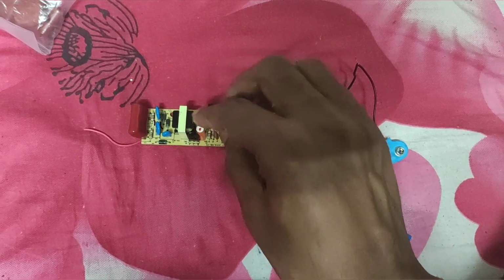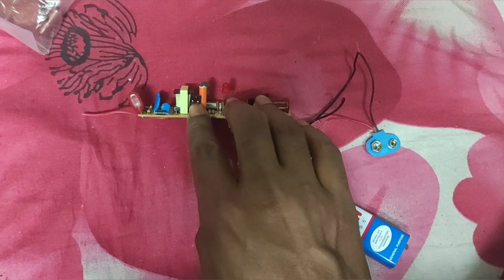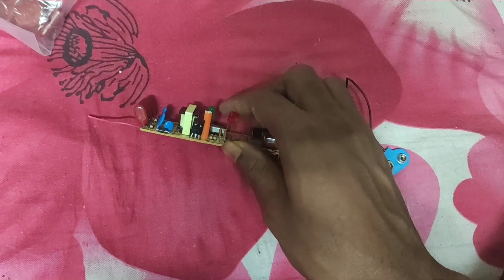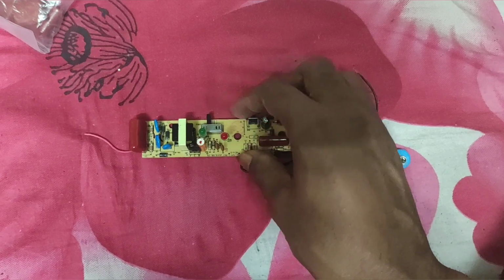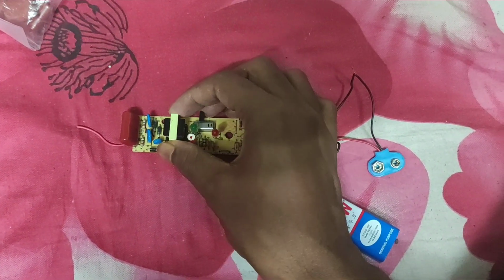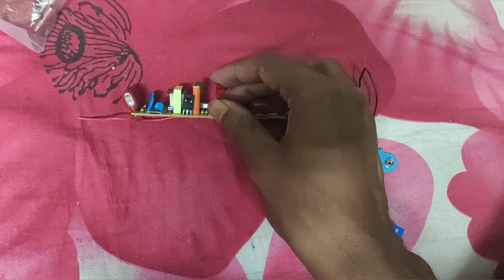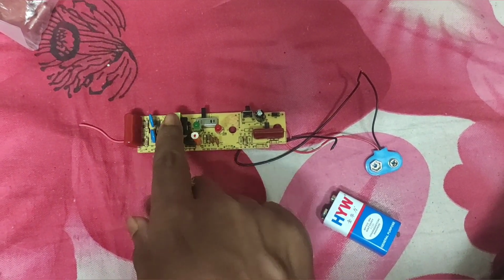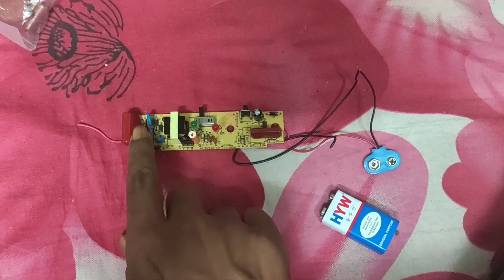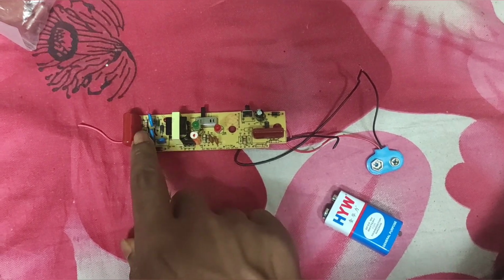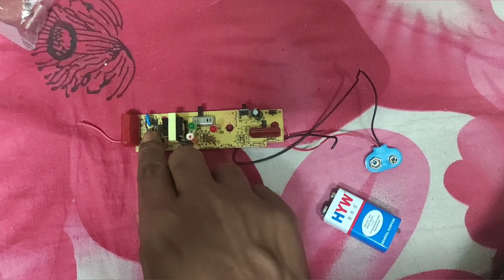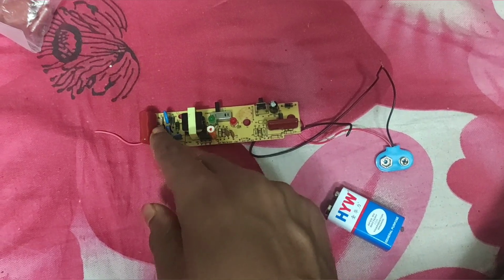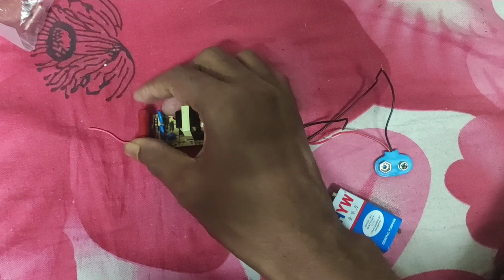The transistor converts this DC signal from the battery to a high frequency AC signal, having a frequency of near about 4.2 kilohertz. So it has a very high frequency, and this iron core transformer converts the low voltage to high voltage and low current. Then it moves from this transformer to the capacitors, which are again used for filtering the AC signal, and again there are 2 or 3 diodes. It rectifies it to DC, and then the DC signal gets stored in the capacitor.